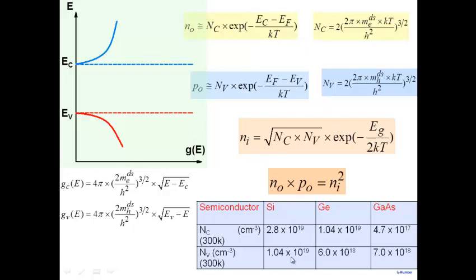On the other hand, if you note the density of states for another semiconductor, especially gallium arsenide, it is a very important semiconductor because it's a direct band gap semiconductor. Remember we had a discussion that the conduction band minima and the valence band maxima lie at the same K value here. And it's important because you can get light emission from gallium arsenide. Also, gallium arsenide has significantly higher mobility than silicon. Mobility values are larger, so it can be faster than silicon.